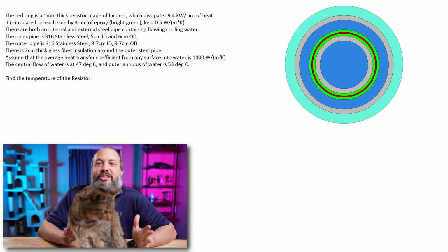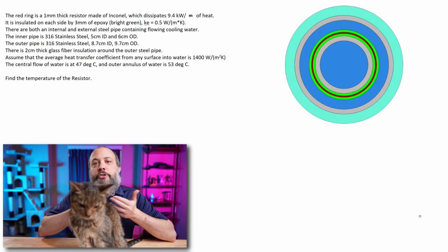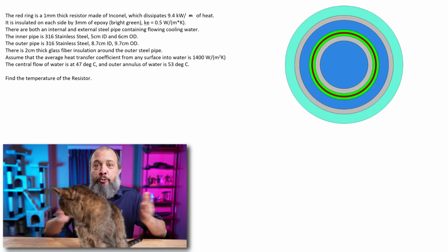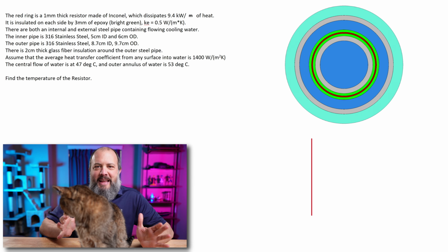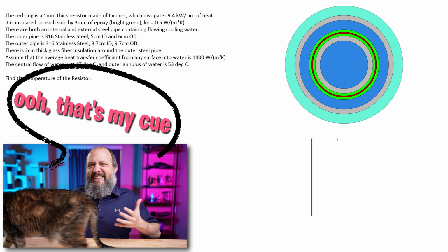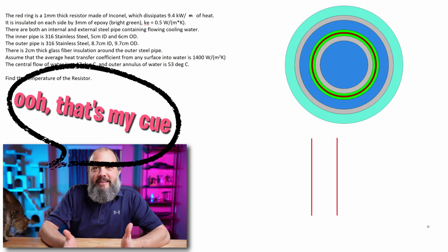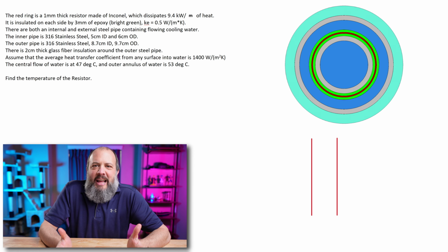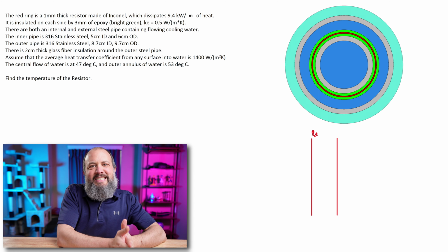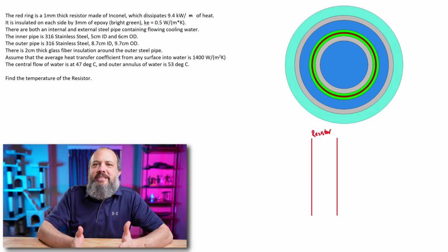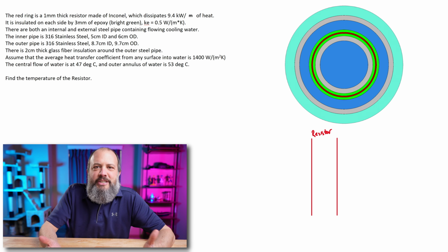And my recommendation for cylinder problems is to make your drawing as if they're just a regular wall. It's going to let you make a bigger drawing that's just a lot easier to see and read. And you just need to remember to actually include the cylinder resistances instead of the straight wall resistances later when it comes to actually plugging numbers into equations.